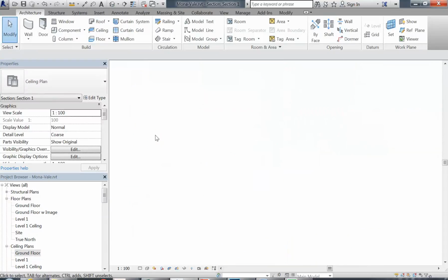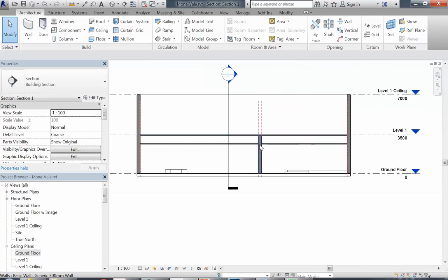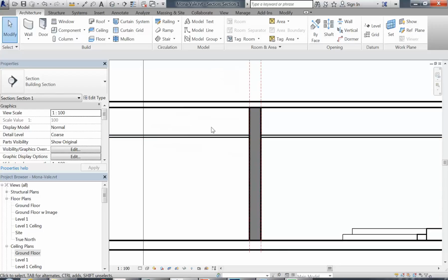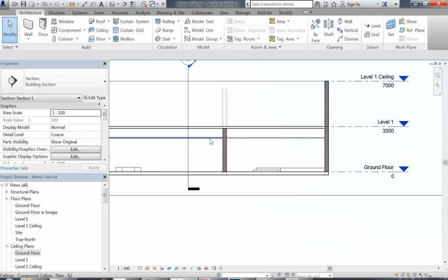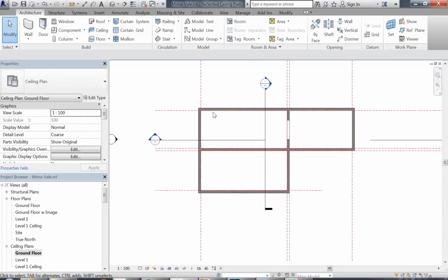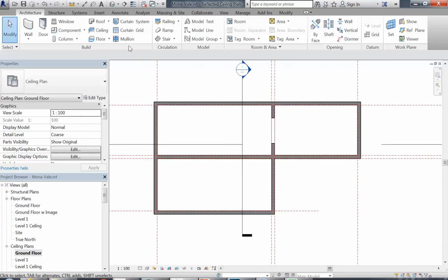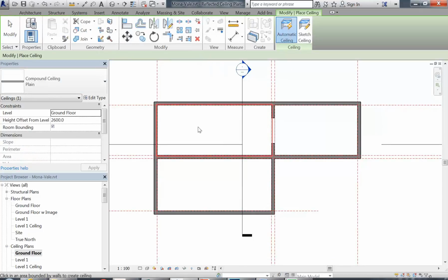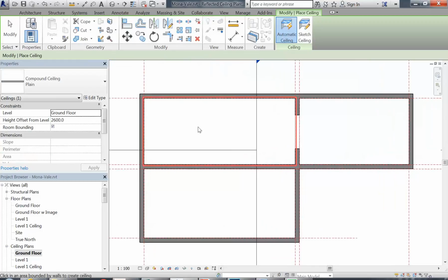What do you do if you've got different ceiling heights? Yeah, then you've got to do something more. So, yeah. But that's going to give me a simple ceiling in each of those spaces. I didn't even think about the height because I'm going to come back and adjust that now. You even didn't pick up the interior wall. Well, I did it automatically. So that's what I'm showing you. If it's a simple space like this, it is automatic. So I'll just show you again what happened. When I clicked on ceiling, then hovering there, you can see it highlights in red when it detects a room.